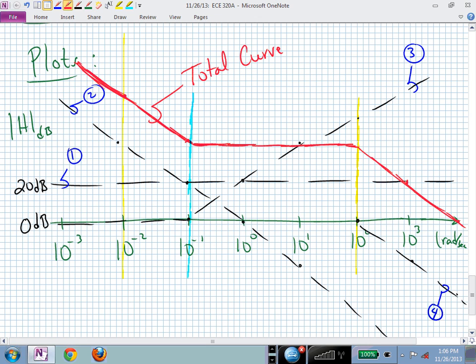I could say, what's the slope at high frequencies for this system? And you would say, in magnitude, the magnitude slope at high frequencies, I'd have to say magnitude or phase, you're rolling off at 20 dB per decade at high frequencies. High frequencies in this particular example means above 100.